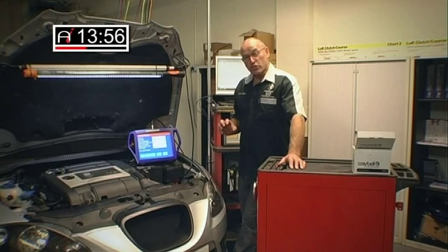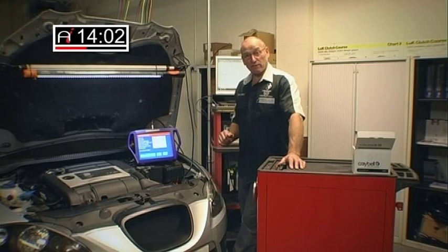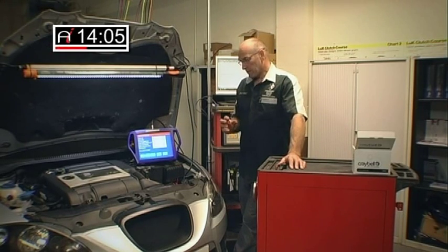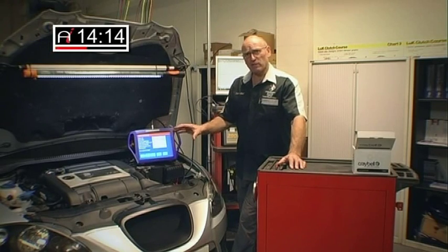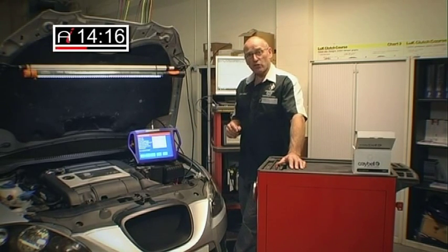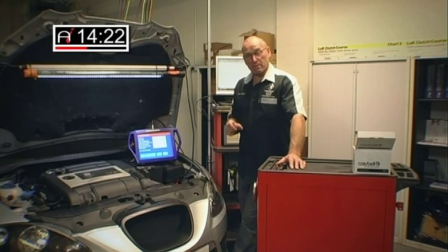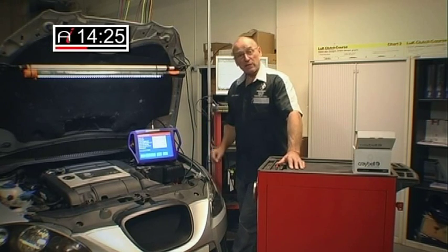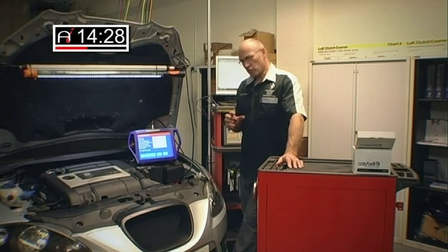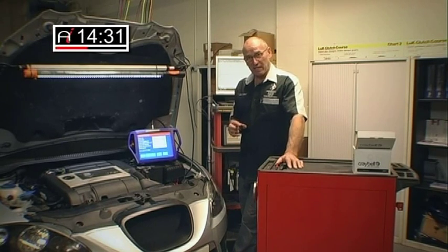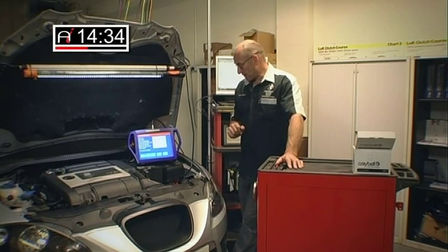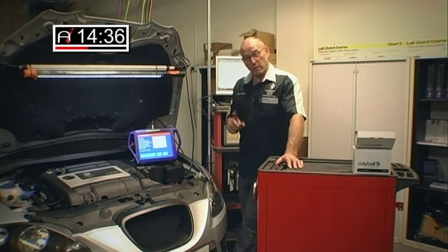But really, for intuitive testing on load, drive the vehicle and look at the specified and actual values of load and the actual air mass meter value. Out of interest, if you take the engine brake horsepower, this is a standard 265 horsepower engine, and multiply it by 0.8, the result of that calculation should equal the maximum air mass meter value in grams per second on full load. So if you're never sure what the air mass meter full load value should be, you can always work it back from the brake horsepower, and it does tend to be quite accurate, with one exception.